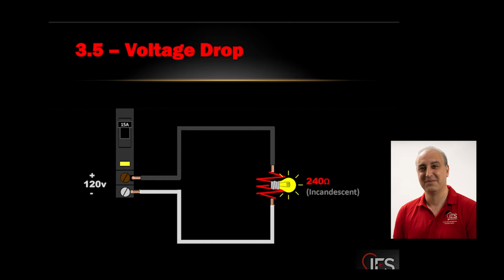You ever notice in the panel, you have two separate buses, right? And you bring the two hots, you drop them in. They're completely separate. If you short circuit them, you get a kabang. It's going to be fireworks, right? Because they're both 120. How do we get 240 between them? It's probably circuit theory 2 that we cover this, but they're flipping exactly opposite to each other. So when this one's positive, this one's negative. And then when this one goes negative, this one goes positive. So the difference between them is always 120 plus 120 gives you 240. But that's a little bit too advanced.